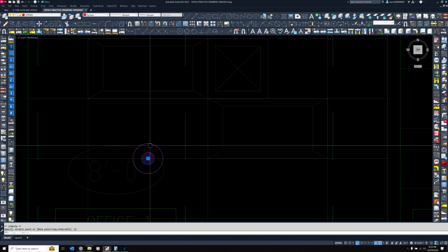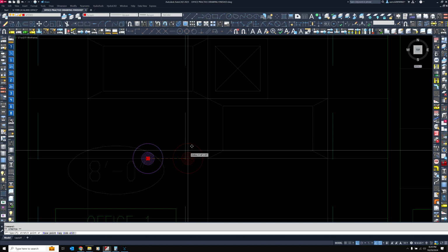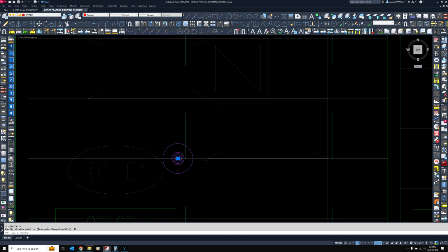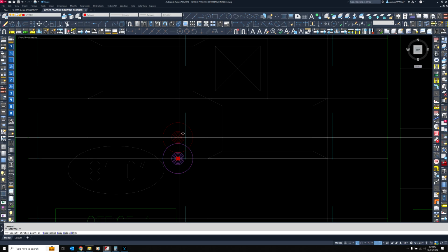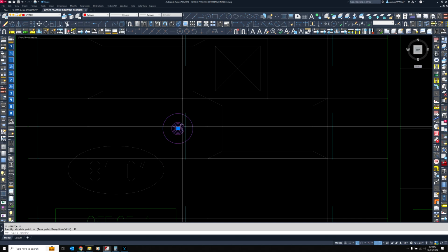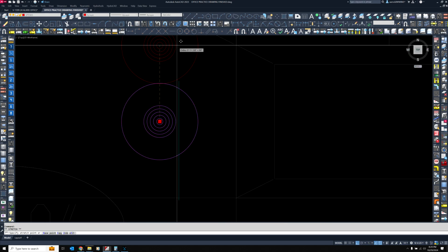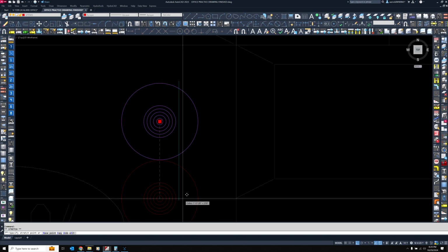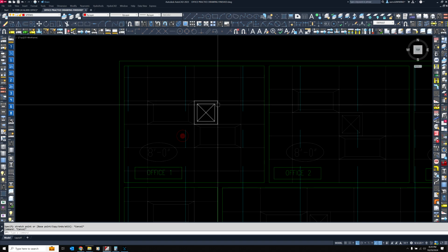Centered would be 2 feet off, 12 inches down. In this case, we're not saying center a tile, we're going quarter points. So we go 12 inches off that intersection, and now I want to center myself between this 2 foot dimension. So let's go 12 inches to the north, and now this head is exactly what we did, 12 inches that way, 12 inches that way, and 12 that way. I know that this sprinkler head in this room is now sufficient based off the size.